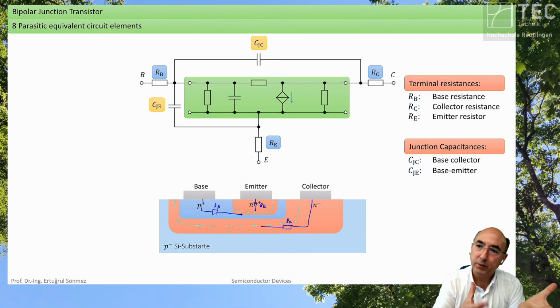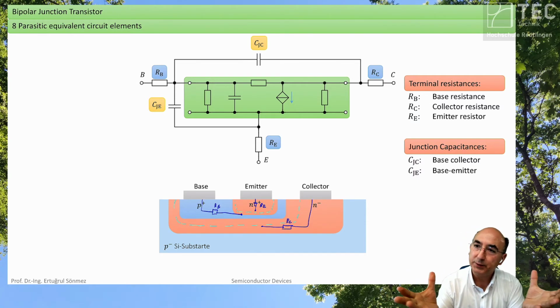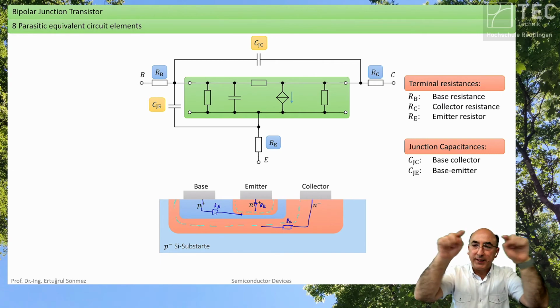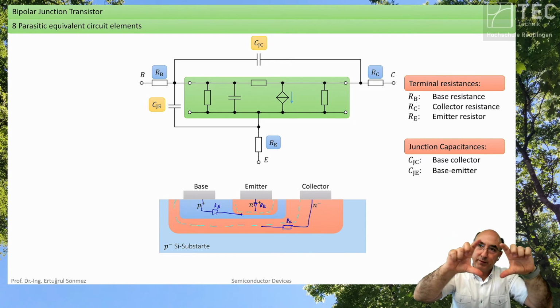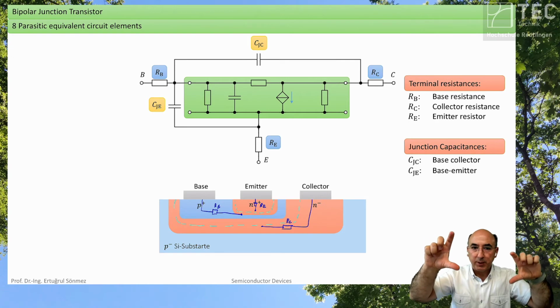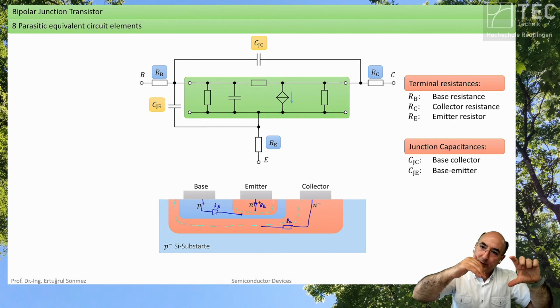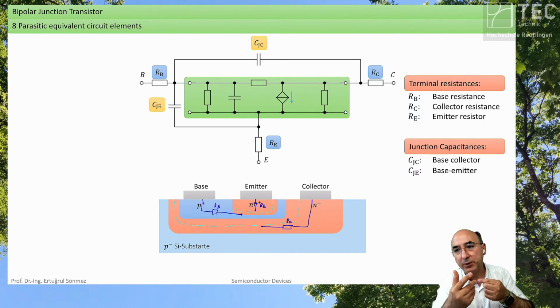And if we take a metal, an oxide and a semiconductor, we have a stack of different materials. Our reference was the vacuum level. We said that the work function is equal, so we have a flat band condition. Then we asked what happens if we apply voltages. We have bending of the band edge, and if the band edges cross the intrinsic level and the Fermi level, then we invert the condition.